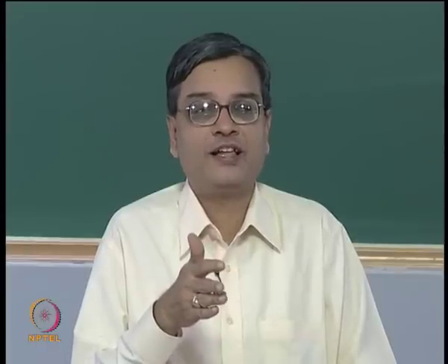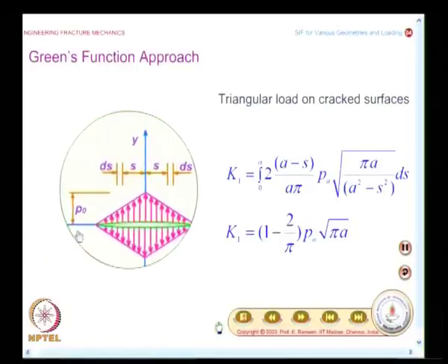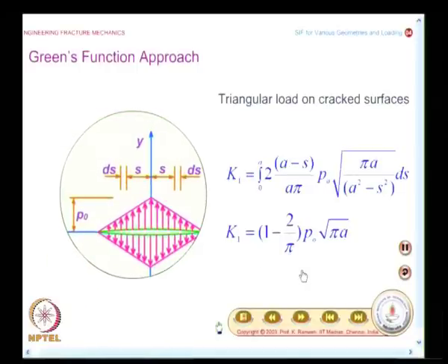And what you find here, whatever the expression for stress intensity factor for a center crack subjected to uniaxial loading or biaxial loading, because we have always said the stresses in the horizontal direction is not contributing to the quantity k, the k is still not affected. There you got that as sigma root pi a. You have an expression very similar to that when the crack faces are opened by pressure. See, here we have looked at a mathematical approach and then got the expression for a distributed loading as well as for a constant pressure.